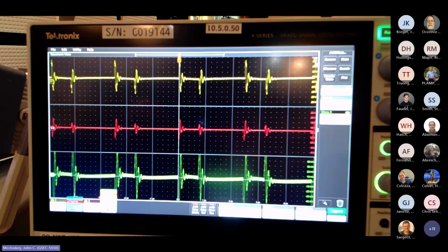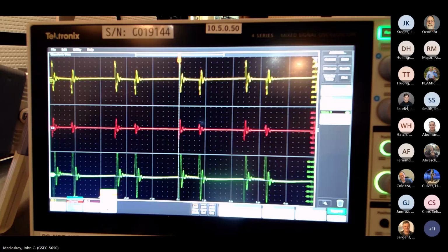Pre-calibration is crucial. That's for characterizing what you're injecting. Right? You're injecting a potential, and then the current is going to be determined by the impedance of the loop, which you don't have any control over. Really, it's just whatever the impedance of the loop is formed by the cable under test in the ground plane. But you establish at least that open circuit potential during the pre-calibration step, and then you're monitoring the current basically to verify that you are indeed injecting a signal.